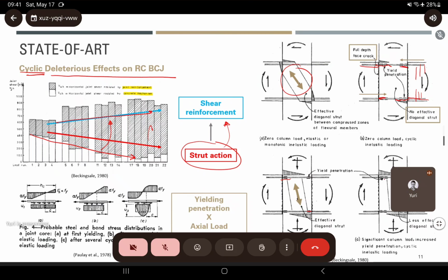And what that does is thin the strut, so you would have less strength taken by the strut. Okay, and this is when it happens to switch. The crack starts propagating and you have less strength of the concrete. So the models that we have in literature, there is a great debate specifically because of this effect. This is why we have much inaccuracy in shear strength predictions.